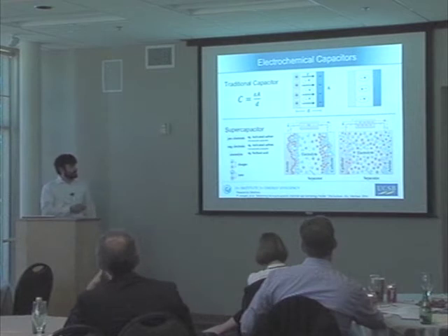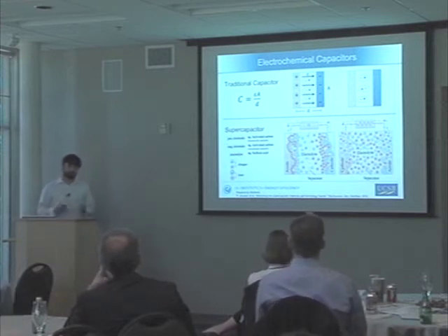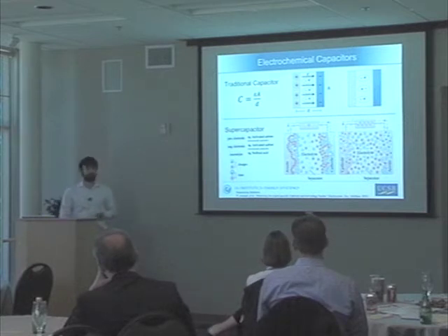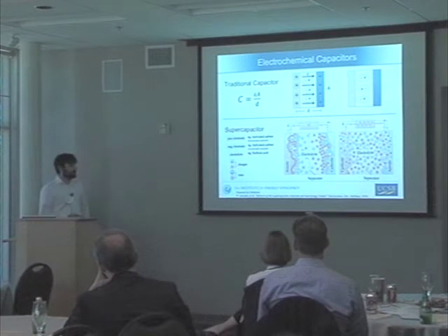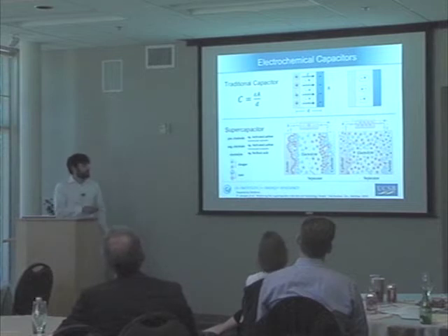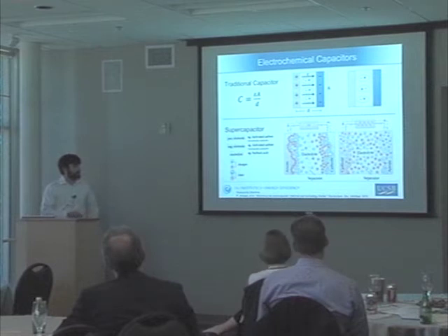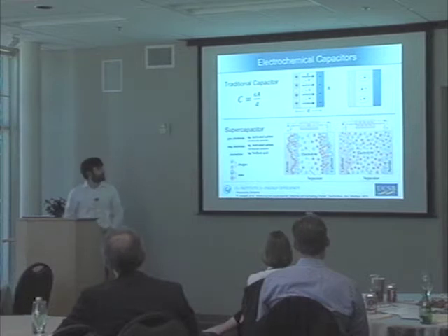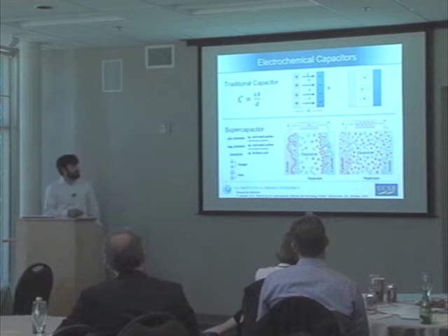There's a trick with supercapacitors to get around these obstacles naturally. Supercapacitors are very simple. It's just two activated carbon electrodes, a cheap material similar to what you find in a Brita water filter, submerged in an electrolyte. It can be an organic or aqueous electrolyte with dissolved salts. As you build a positive charge on one activated carbon surface and negative charge on the other, you separate the cations and anions in the electrolyte. You're storing energy in the electric field between this layer of dissolved ions and this layer of surface charge, and it acts as two capacitors in series.